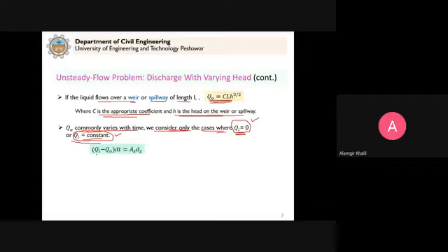So now we come back to this equation. Now we are clear about all the terms. This is the change in water level. This is the surface area, no problem. This is the time dt. And now we are clear about Qi and Q naught. So what we can do is write down dt equal to A dz divided by Qi minus Q naught.